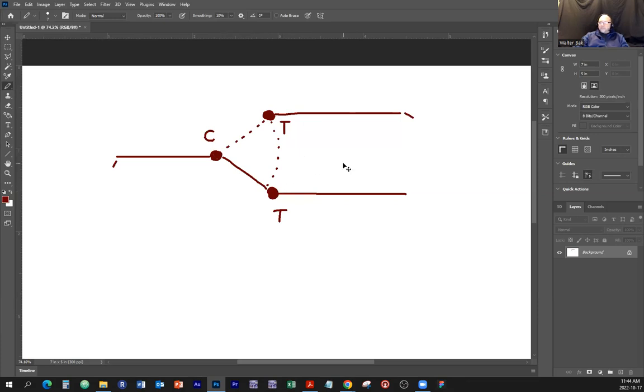Now, if we put a continuity meter between this point and this point right here, no matter which way we flip the switch, these two will never be connected. So you only have few possibilities to connect your meter to it. And if you find the two of those three that no matter how you flip the switch, they never make connection, then you know that these two are travelers. So the third one must be common.